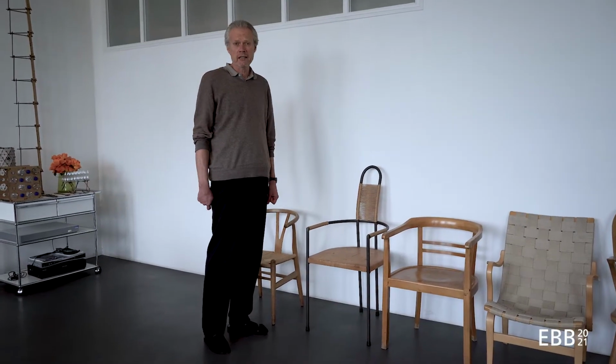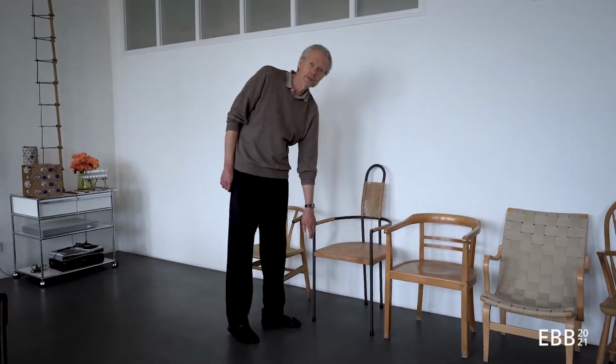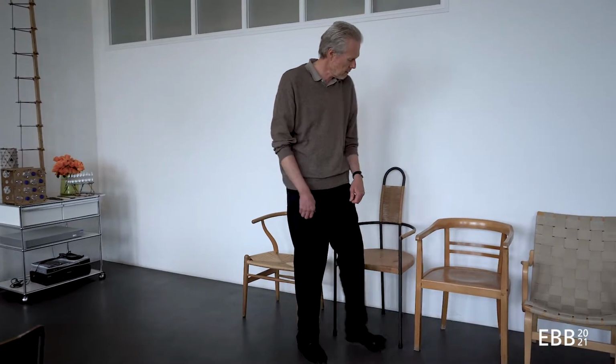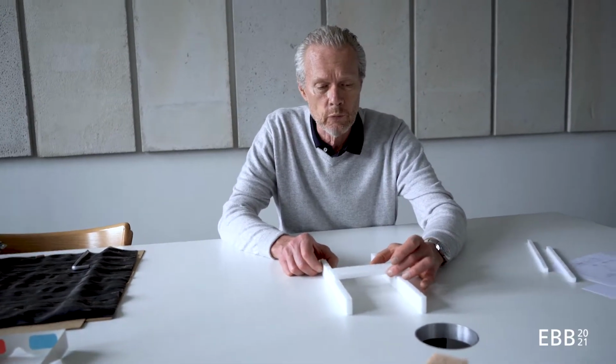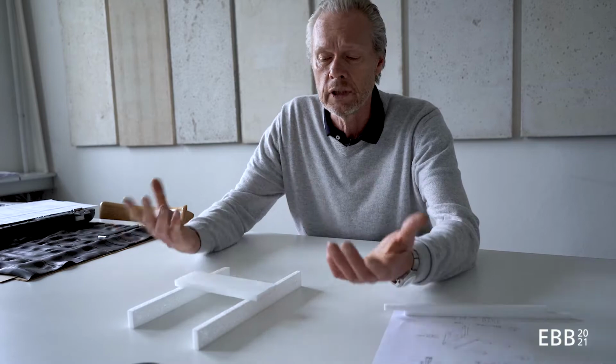So here's a chair I designed a couple of years ago, and it has a horizontal structure made out of wood, massive wood plate, and a vertical supporting structure out of steel columns. And the objective is to create a surface that I can sit on. If I have, for example, two walls, and I want to span from one wall to the other, I will use an element to form a surface. And you can remember that for a plane element like this one, it's about 1/35 of the span that I have to calculate for the height in a real building.